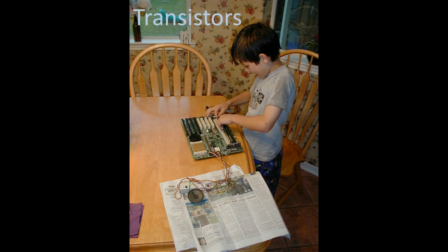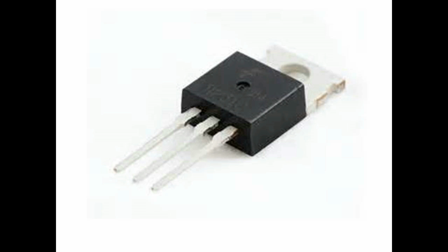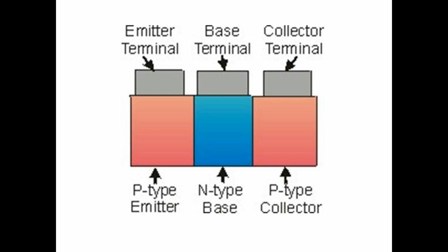Transistors are the essential building blocks of modern electronic devices. They are a semiconductor device that can amplify and switch signals and electrical power. Transistors have at least 3 terminals that connect to differently doped semiconductor materials. The transistor allows a large current to flow from the collector to the emitter only when a small charge is placed on the base from the emitter. Therefore, you are able to control a large current with a smaller current.